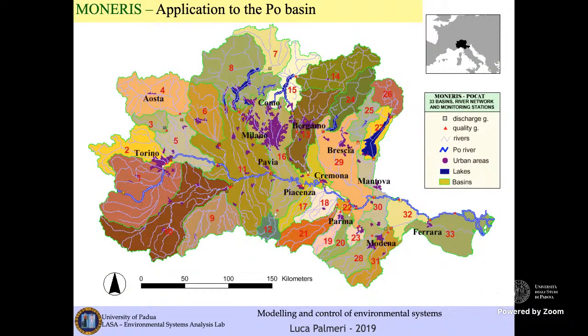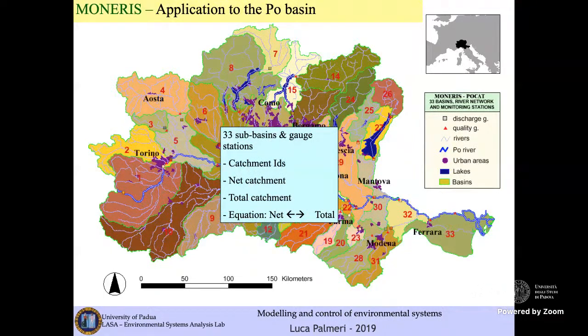And then we said that we gather all this information concerning the subbasins. So the subbasins of the model, or the hydrological subunits, are 33. In this case, for each one of these 33 subbasins, we need to find a good station for which we need to have information on discharge and information of the surface that is contributing to the catchments in terms of discharge.